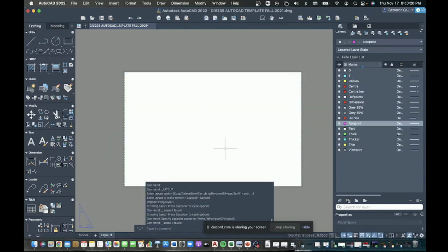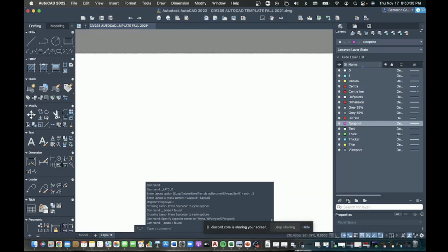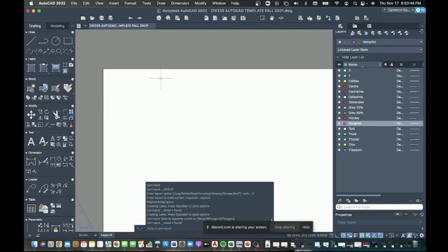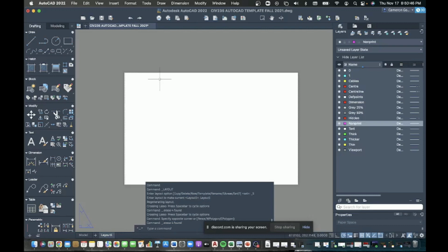And you should have something like this. So now it probably looks like your space now. What I can do here is insert a viewport. What a viewport will do is allow me to place my bridge on this paper space. What we're essentially doing is taking what we've modeled and putting it on a finite space as opposed to the infinite model space.